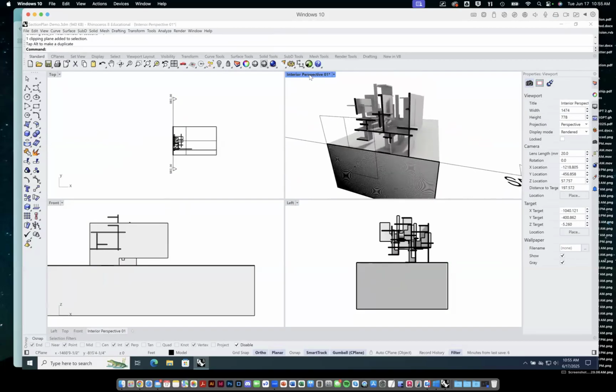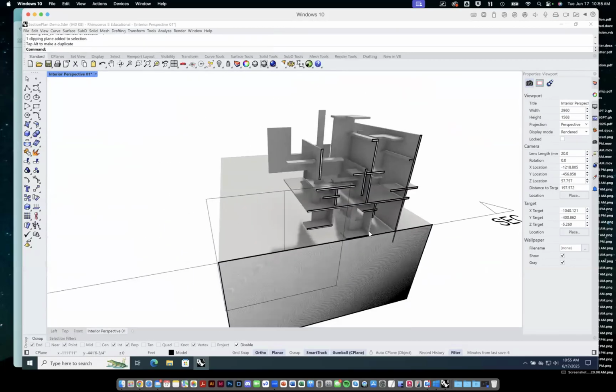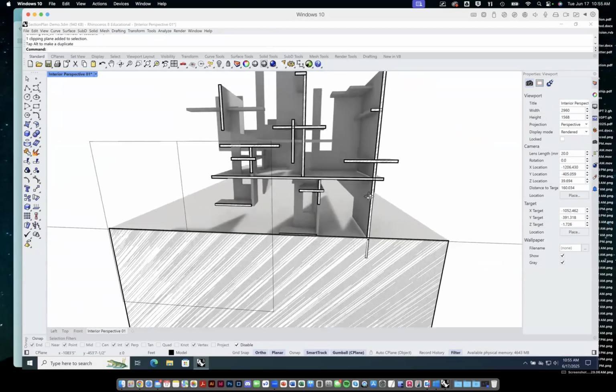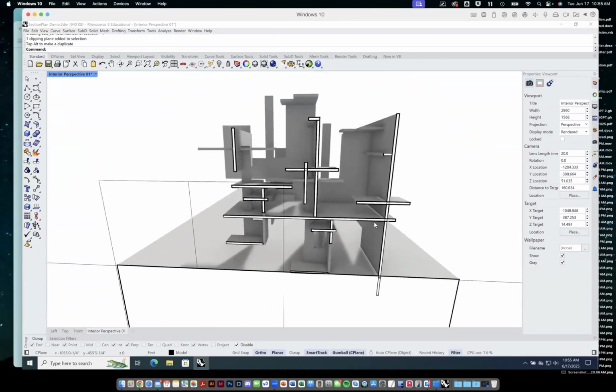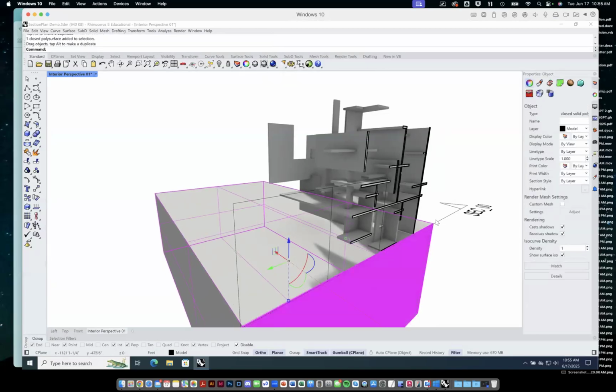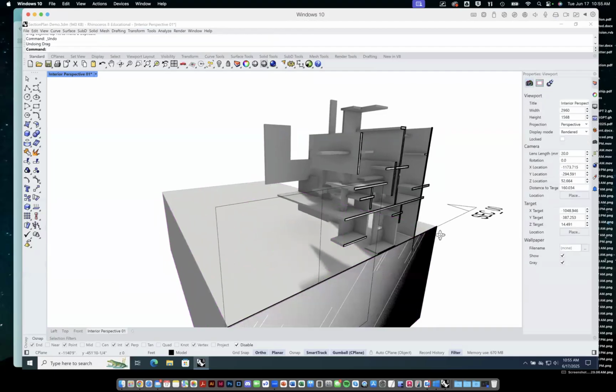I'm just going to go back in this perspective so we can see things three-dimensionally while we're cutting them. Sort of makes a little more sense here, right? The conventions for cutting a section or a floor plan is that first of all, we prioritize walls, ground, whatever is being sort of cut through, right? And then sort of x-rayed through, right? So in this case, walls, roofs, floors, etc., the earth, even the ground is being cut through. And so that's what we would draw first.